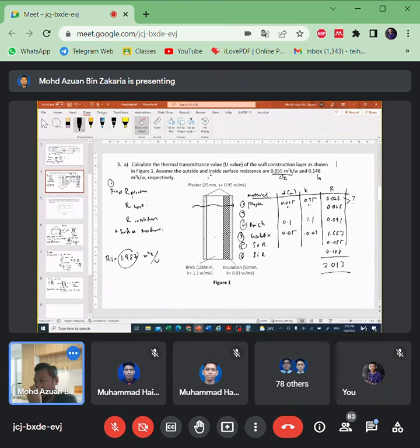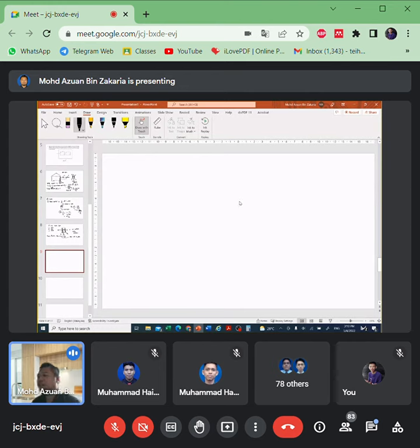for an actual report, my arrangement is actually not good. But in future, if you want to submit for green building certification, they will see your arrangement of layers. So the best way is to start with surface outside resistance, and then number 2 plaster out, and then number 3 brick. So the arrangement must be logical. Number 4 must be insulation. Number 5 must be plaster in.